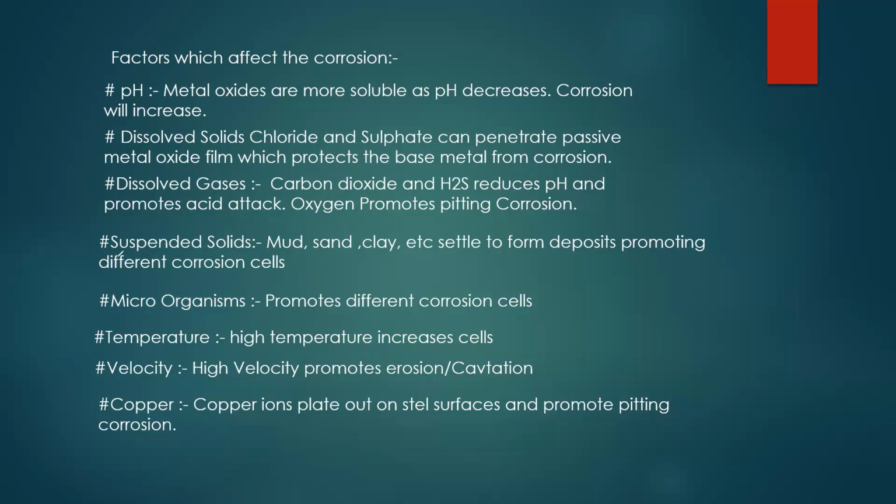Next, if you have suspended solids, mud, sand, clay, etc., they settle to form deposits, promoting different corrosion cells. So we are talking here about electrochemical corrosion, right? Yes. And these all react and form oxides and make one metal differ from the other, although they are the same metal. Next one is microorganisms, which promote different corrosion cells.